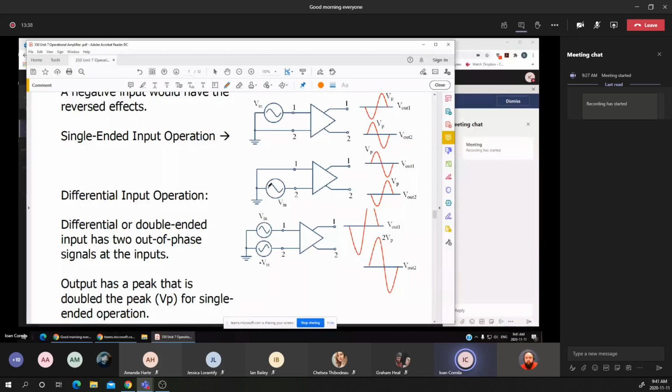You notice that as the voltage is increasing at this stage on the second base of the transistor, or the second input, it will decrease the output voltage, or the collector voltage on the Q2, and the effect on the Q1, with the same voltage, is that it will increase the output voltage on the Q1.